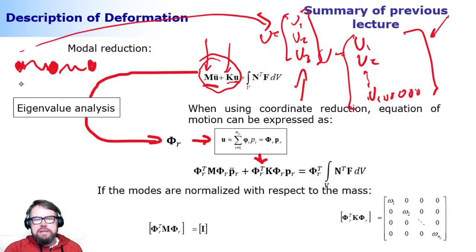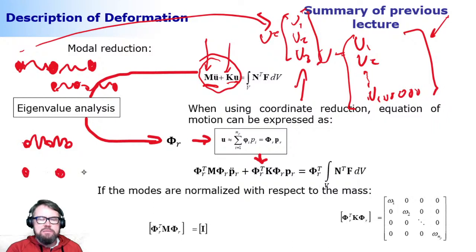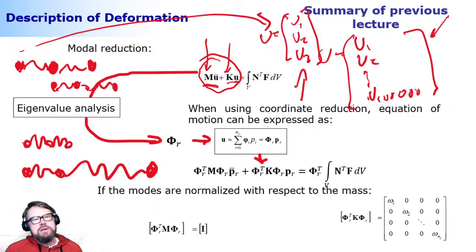The way this can move, of course, is the possibility of rigid body motion, meaning that they all move left or right without any spring deformation. Then one possible way they can move with respect to each other is that the structure gets smaller, like this. One additional way is that these two get closer to each other while these two get farther from each other. So these are the deformation modes. These are the ways the structure can deform.